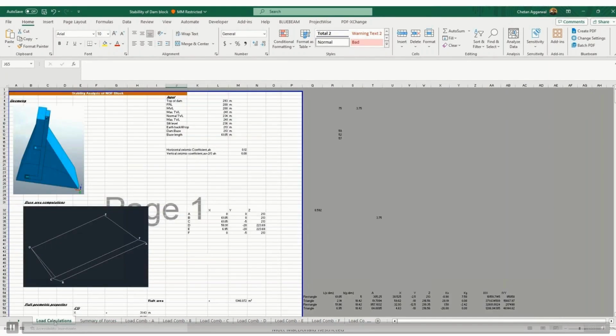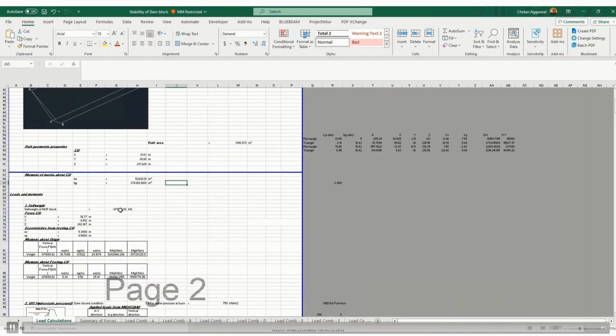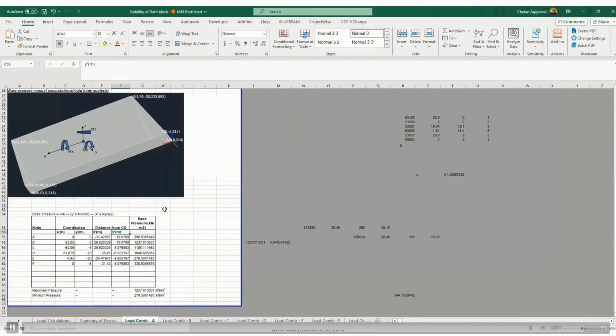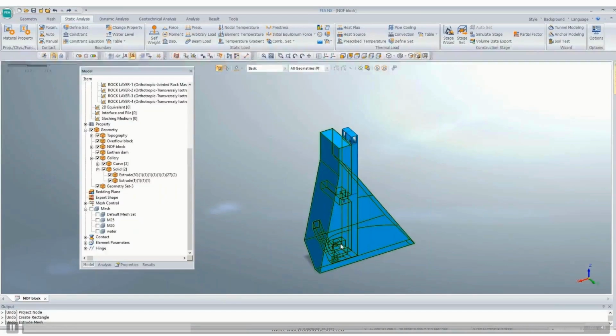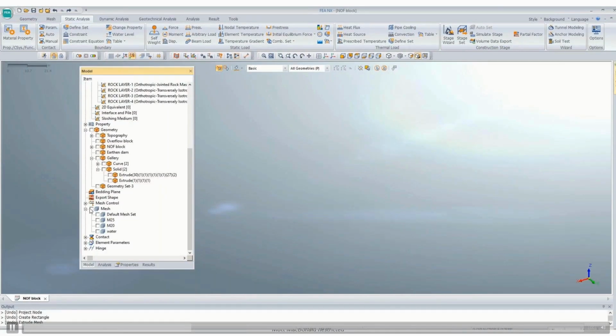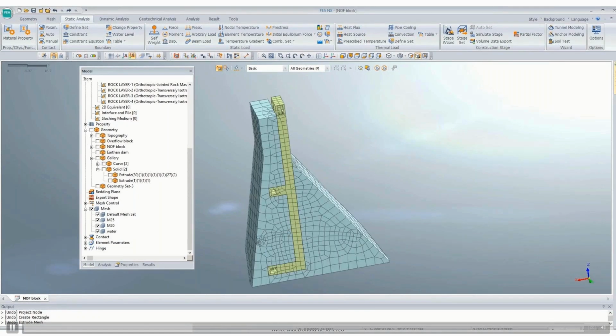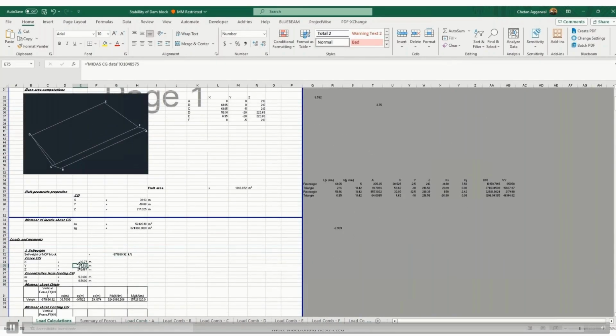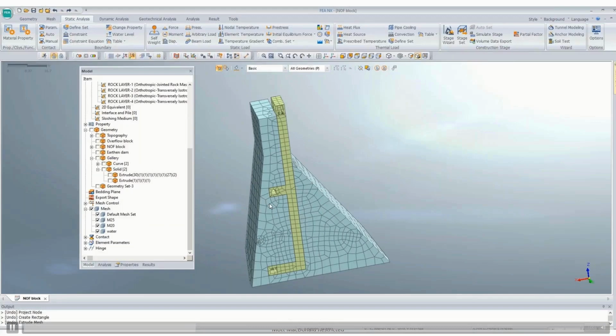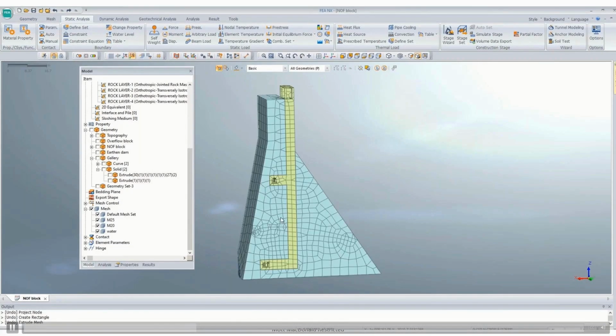For compiling it here, say for self weight, it is in the negative Z direction, the direction of application of load, so this will be negative. Say the CG of this load, for the construction condition, will lie somewhere here. You can check it from the Excel sheet. The CG is at 36.77, the total length is 61, so about 37 meters, it will lie somewhere here, and minus 9.5, somewhere here, and 242.67, so it will be at the upper location, 242 point whatever we have evaluated.